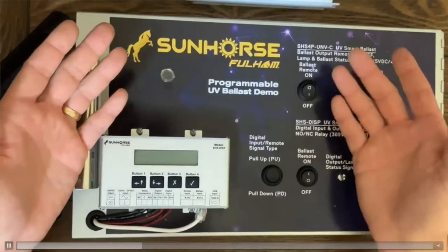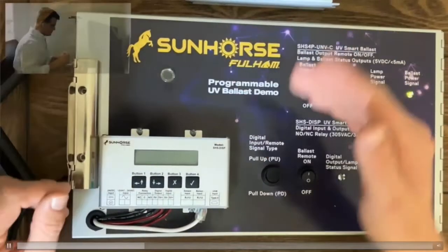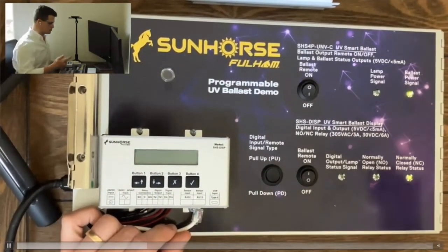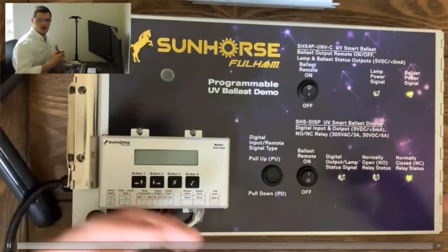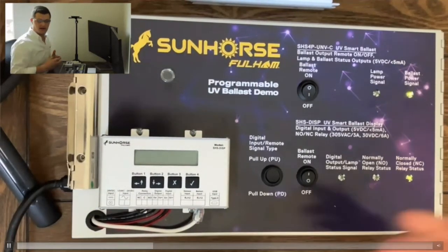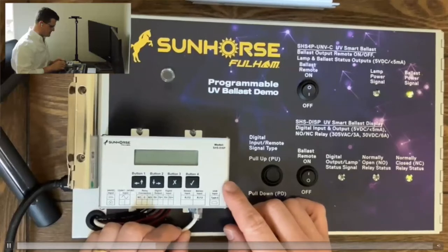Or by closing the dry contact, it will disconnect the lamp and the ballast will remain powered. So a really cool little feature that allows you to either make a safety interlock or connect to a control board, or perhaps disconnect a large group of ballasts without creating an inrush current problem. A really great feature that we added to give flexibility to OEMs who want to access some level of intelligence without having to use a display or an I2C.